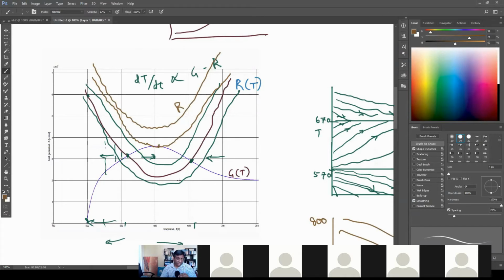Does there exist a T inlet value that we have to worry about? We can say yes. If we manage to get a value that caused a tangent here, that would be the point where the system loses those two steady states, and the system would always be killed. We'd try to start up that reactor, and the temperature would just drop and kill the reaction. So there does exist this temperature T in where this could happen. The question then is, how could we determine that value?